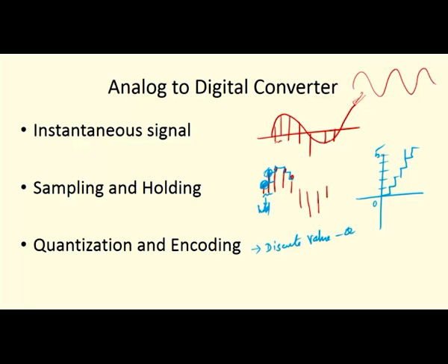For quantization, suppose 8 bit: the 0 to 5 volts will be divided into steps, that is, we usually compute V out divided by 2 power 8, that is 256. So based on the number of bit positions you can divide it; this is the step size of the quantization. Based on this we can define the resolution of the conversion. After getting the discrete value, the corresponding discrete value will be converted into the required binary value. The conversion of discrete into binary is called encoding, right.